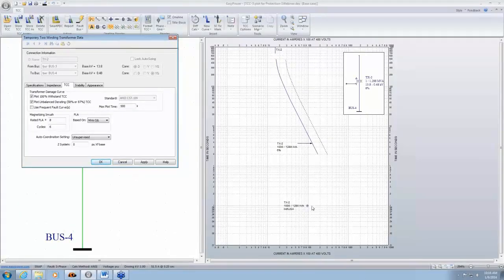And towards the bottom here, you'll see a small circle with a dot inside it, and it says inrush. So whenever you energize a transformer, initially you get considerable inrush current because of the magnetic saturation of the core, and it will last several cycles. By default, we have the value of 8 times full load amps of the transformer seen on the primary side, lasting approximately 6 cycles.